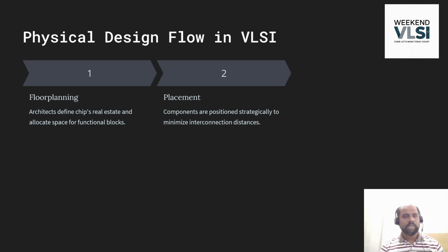One is for getting better timing and getting better power. Okay, power closure. These are the two things which we do, and the main thing or important thing which we take care in placement is to control the congestion in the area and the utilization as well. Okay, so different companies have their own utilization targets. Some people have 60%, 70%. Some people go more than 70% also for their utilizations. And congestion, as the tool vendor specifies, right? You need to have congestion as little as possible.